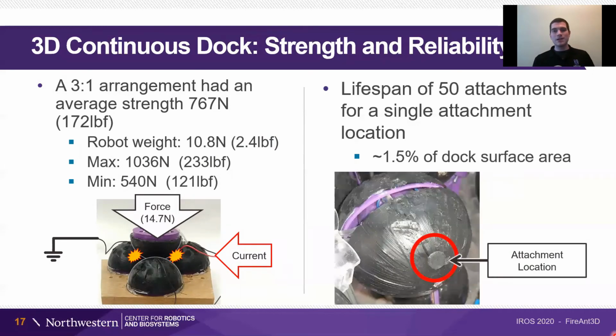The reliability of the docks is also good. During developmental tests, we would attach and detach at a single point repeatedly. And after 50 attachments or so, that's when you started to see the first failures, with failures becoming common after about 100.